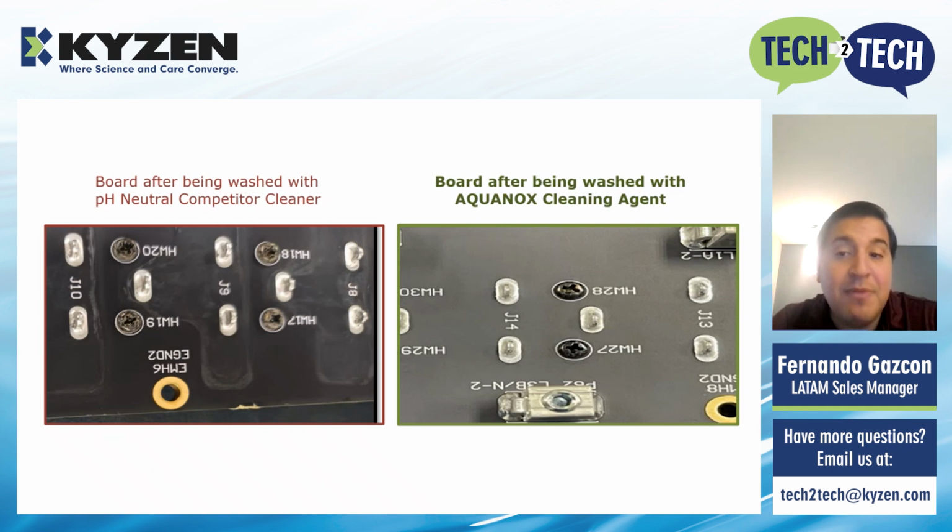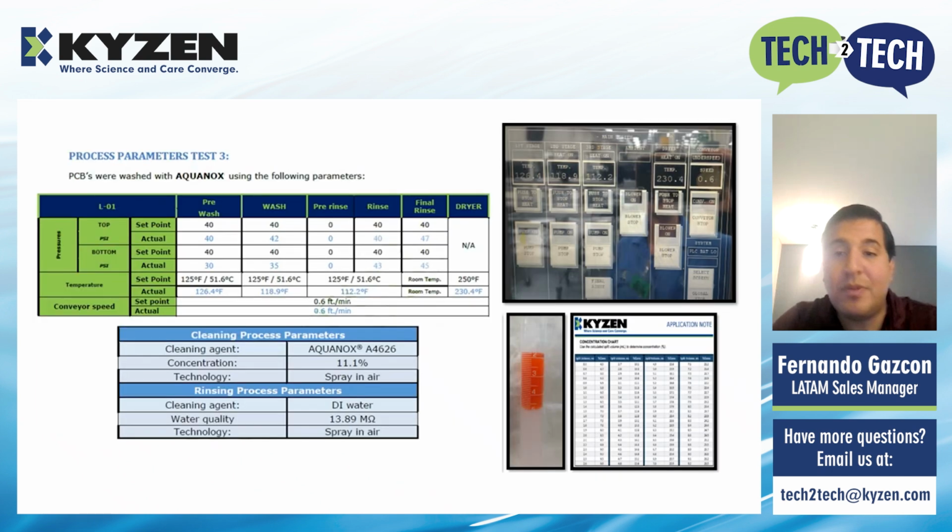Fluxes on the market keep evolving, introducing new formulations that are more challenging to dissolve, hence to clean. You could have used a chemical for the past decade and suddenly start noticing residues being left with new flux formulations. This could mean that your cleaner is not capable of dissolving all the components in the new flux formulation.